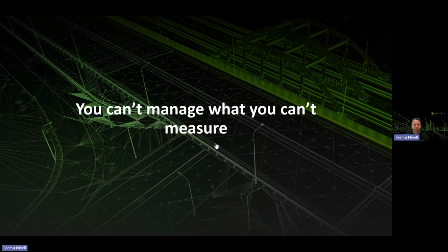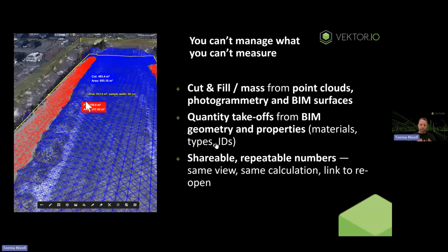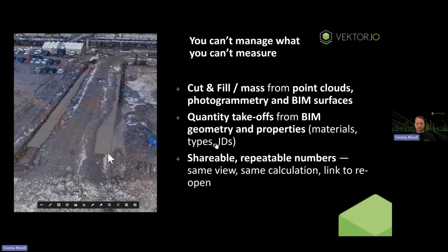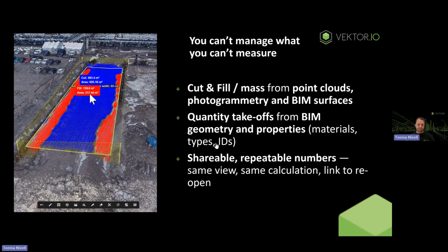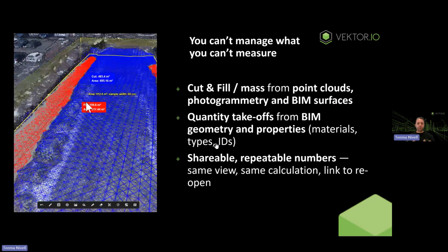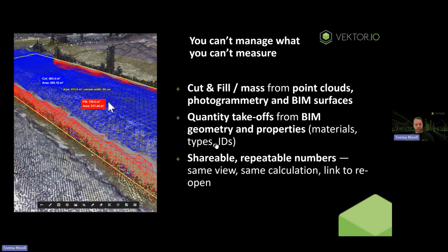Last theme: you can manage what you can measure. This theme is about turning the shared views into numbers you can defend. First, we calculate cut and fill directly against reality capture or design surfaces. Second, we take quantities from the model, both from geometry and from BIM properties. Each result is repeatable and shareable. The same view, the same inputs, the same outcome.